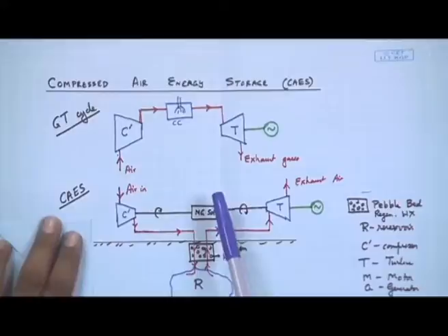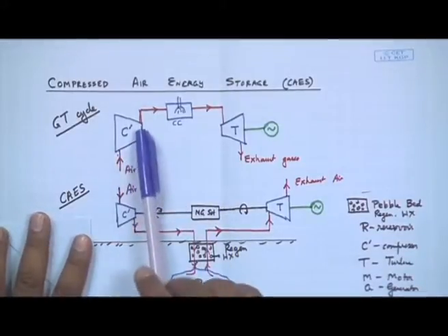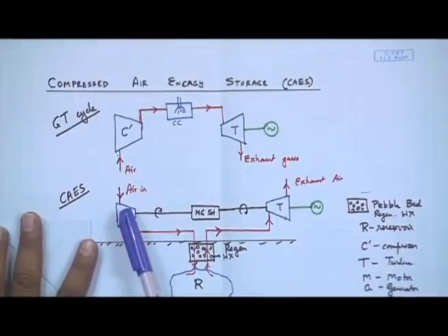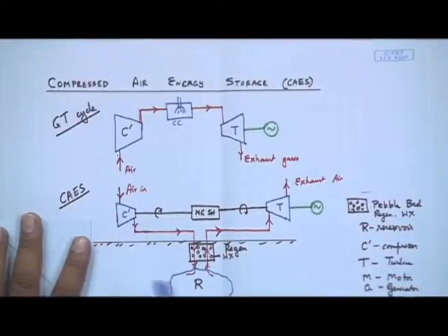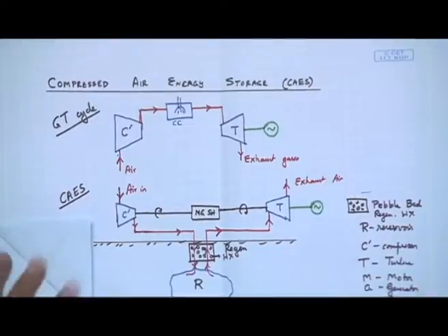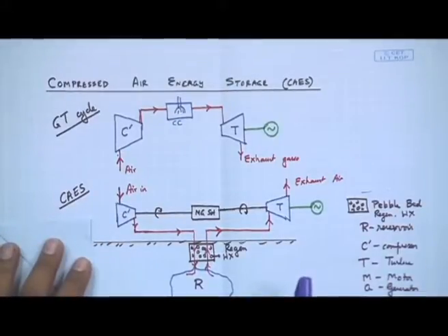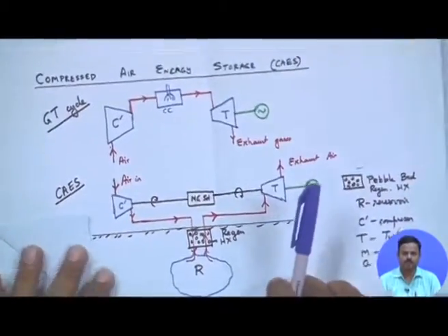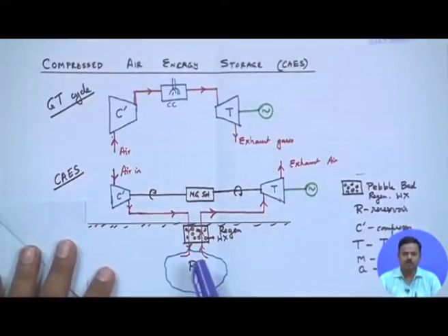These are the schematics that we had drawn, and if you see, what it essentially follows is we have a compressor where air comes in, probably at atmospheric pressure and at normal temperature, and then it is compressed. Now, as the air is compressed, its pressure rises, its volume shrinks definitely, and its temperature also rises. Then that pressurized air is stored in a reservoir. Okay, and we are going to talk about what these reservoirs are.